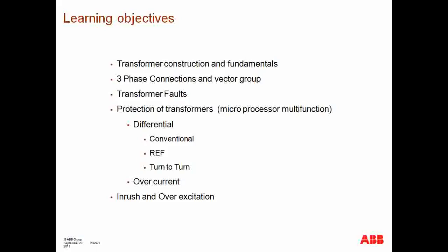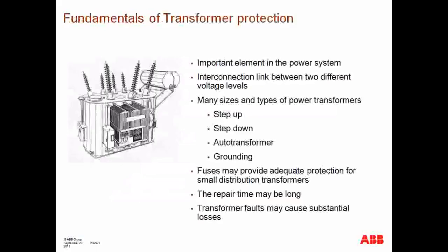So we'll discuss differential protection mainly. And then we'll discuss some backup functions related to overcurrent principles. Last but not least, we will also have a discussion about inrush current and overexcitation, and how those two conditions affect and need to be accounted for in differential protection schemes of transformers. Okay, so with that in mind, let's go ahead and get started.